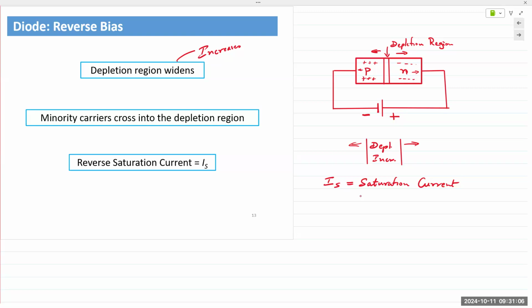You can actually simulate this in the PSpice model. If you take that first diode circuit that I referred to a few minutes ago, one diode, one resistor, and simulate it from -1 to +1 volt source, you'll get a current of about 1 picoamp. You'd have to zoom into the y-axis to determine that, but you'll be able to see 1 picoamp, as close to 0 as possible.